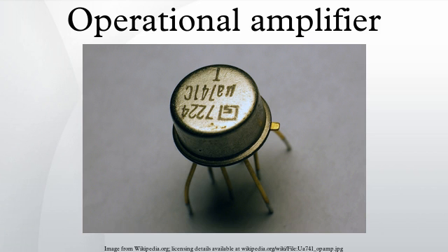The output impedance is not zero, as it would be in an ideal op-amp, but with negative feedback it approaches zero at low frequencies. Overall open-loop voltage gain: the net open-loop small signal voltage gain of the op-amp involves the product of the current gain HFE of some 4 transistors. In practice, the voltage gain for a typical 741 style op-amp is of order 200,000, and the current gain, the ratio of input impedance to output impedance, provides yet more gain.